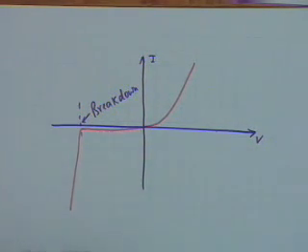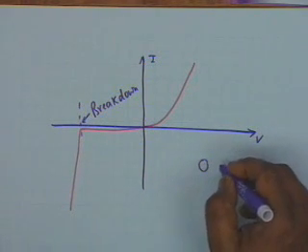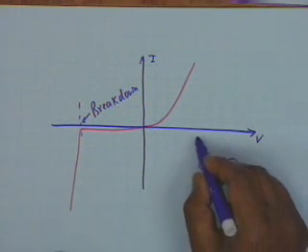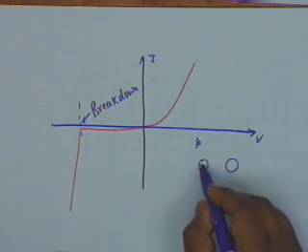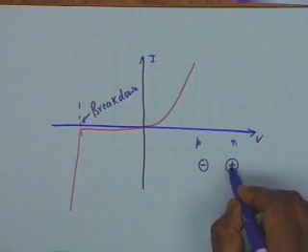Resist, what does it resist? It resists the flow of current. Now, why does this happen? Basically, there are two phenomena that lead to this. One of them is, you know that under reverse bias there is separation of charges. On the P side we shall have negative charges, and on the N side we shall have positive charges.